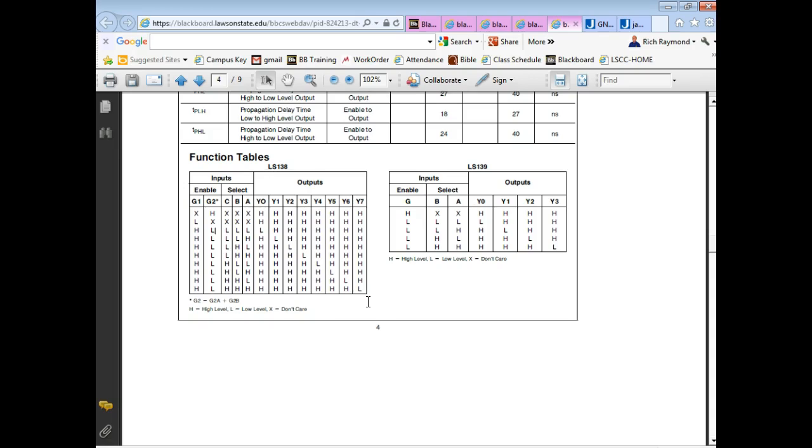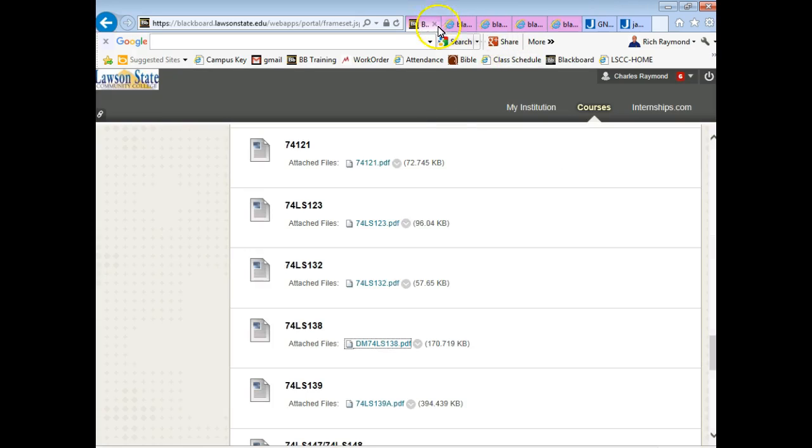Now what's nice about this is that octal only uses 3 binary digits anyway, so we can't go over 7. You understand that? But BCD uses 4. So with 4 bits you've got 16 combinations, even though BCD is only supposed to use 10. So you'll see how this guy works. This is a decoder. It's taking 3 bits of binary and converting it over to its octal equivalent, right? You understand that? Now the 74154.